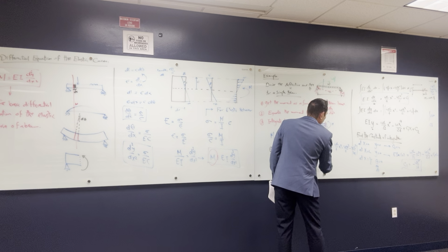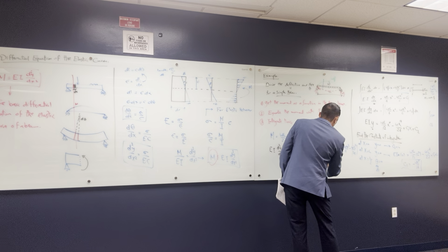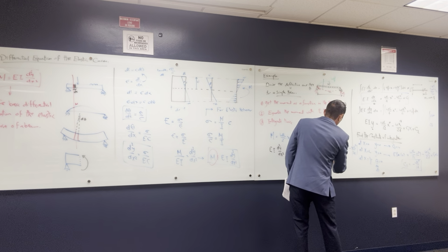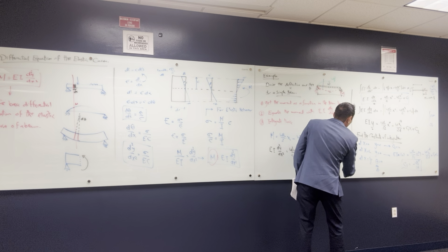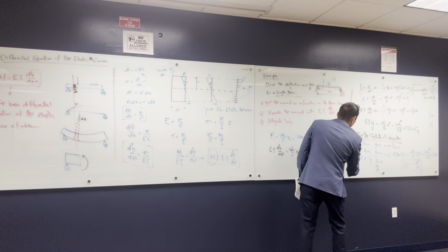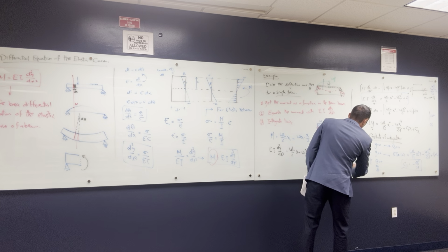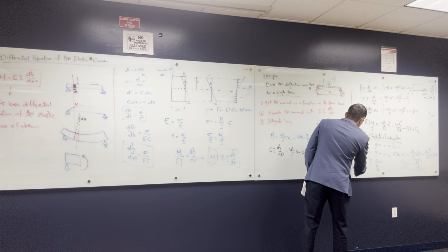The equation of y, same thing. I have here, this is y, I'm gonna divide by 1 over EI. And this is gonna be WL over 12 x cubed minus WX to the power 4 over 24 plus C, which is negative W L cubed over 24 and multiplied by x.